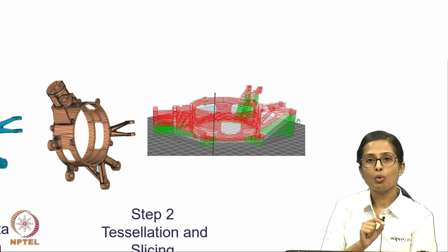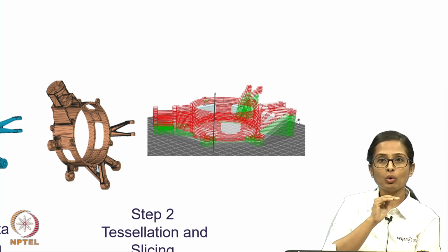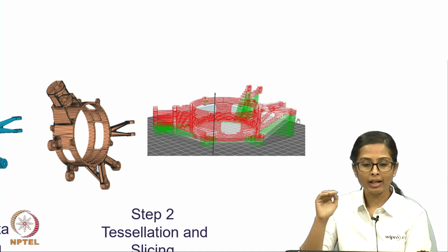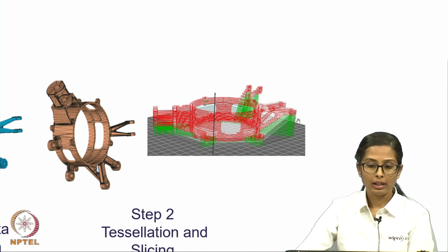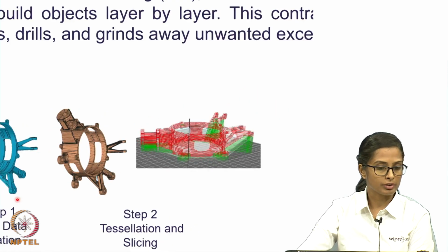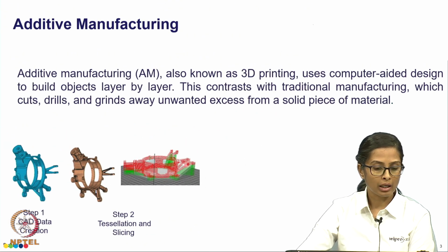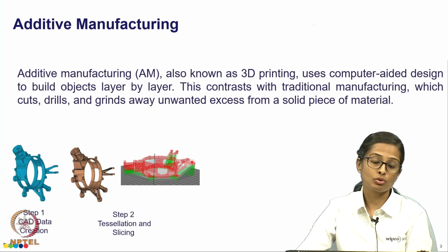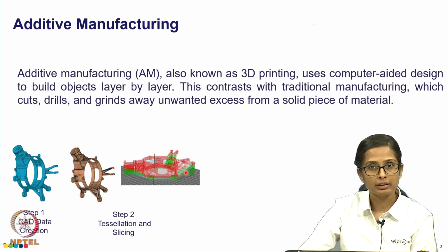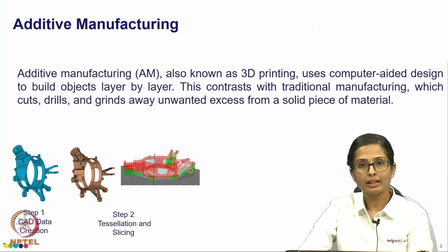So, here what happens is that when you have overhangs that you have to print, right. For example, you see on the right hand side of this particular part here, you are seeing that there is a step, right, and that is an overhang. So, then you have to put supports under it, which is this green part exactly.